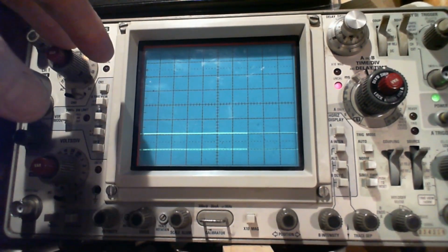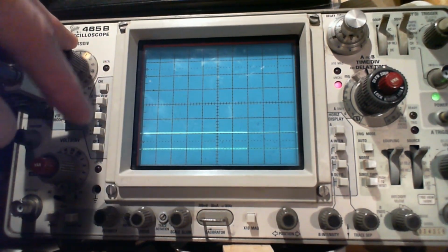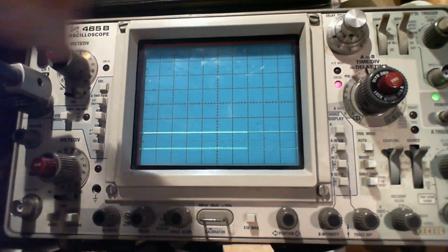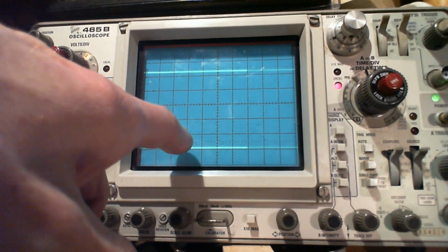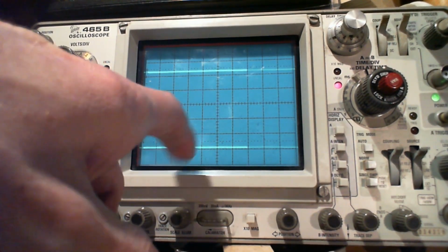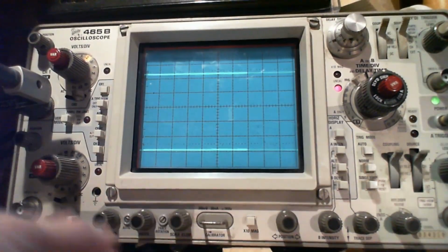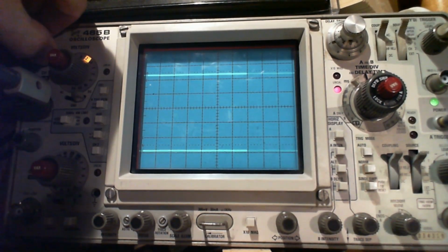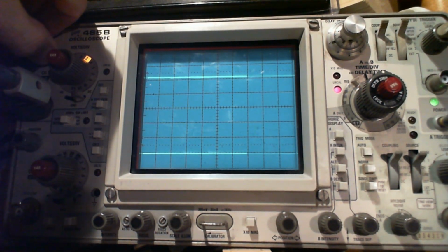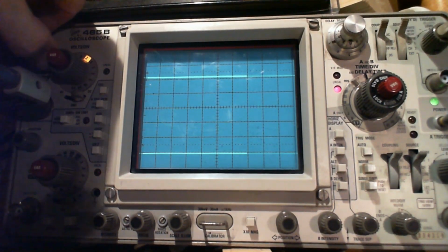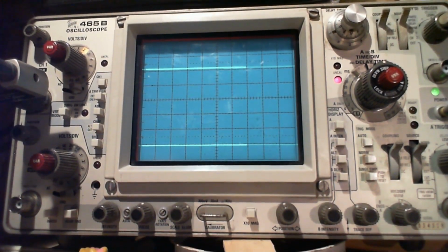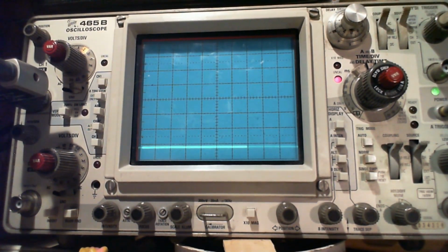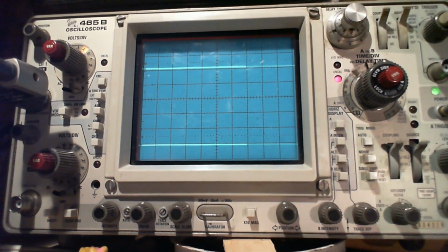Okay, so this is supposed to be 1 volt peak to peak, and I have this set at 1 volt per division. Let's take it up to 2. So there should now be 5 divisions in here, and it's just a wee bit high. No parallax error. So up here, it's slightly high. You want to believe that scope, but I can't, so I can't change it. At least I don't know that I can change it.